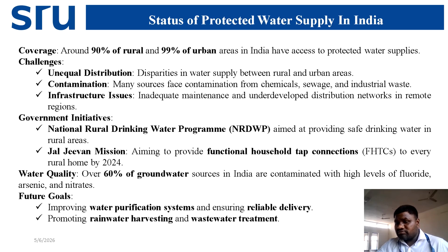And also we can adopt some kind of wetland techniques. Why is it helpful? Wetland will restrict the flow of water. The contaminants present in the water can be taken up by plants, and the remaining water gets filtered and will reach the aquifer. Here water won't flow on the surface, it will be stopped, and it will try to infiltrate into the aquifer.